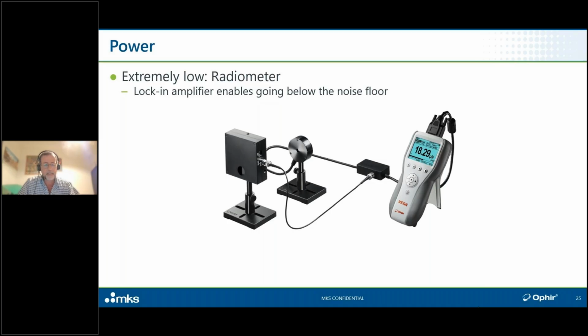And then we use a digitally synthesized lock-in amplifier to pass only signals that are riding on that frequency. The noise and background light is broad spectrum, so almost all of that gets chopped out. So this trick lets us use a suitably broadband sensor to measure signals that are way below what would normally have been the noise floor of that sensor. In some models, we actually can go down to as low as the femtowatt range.